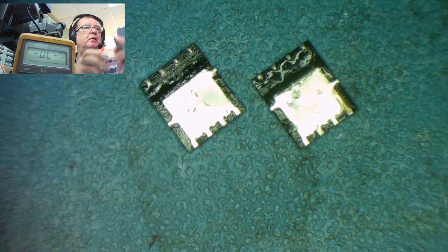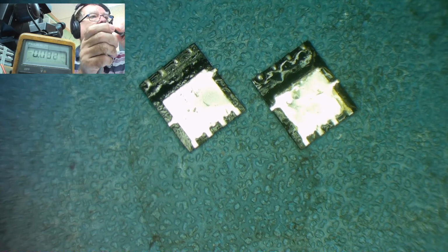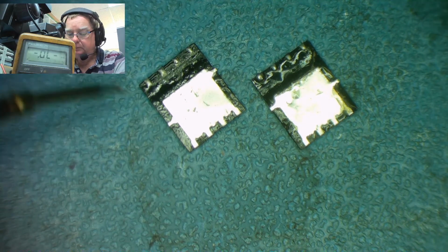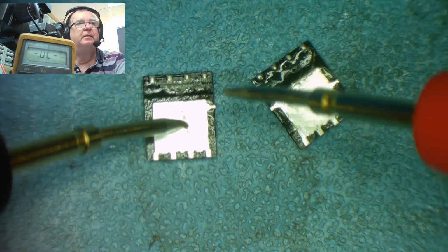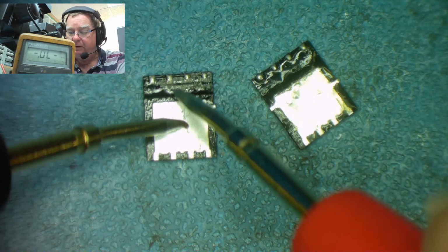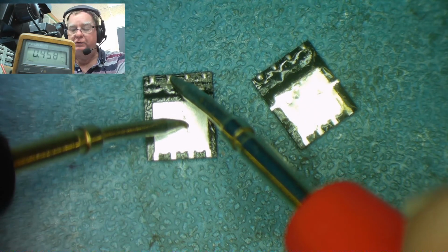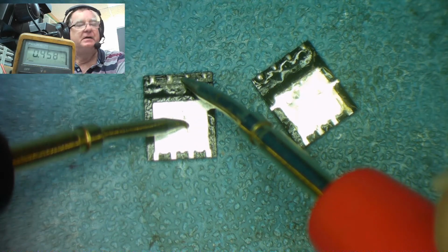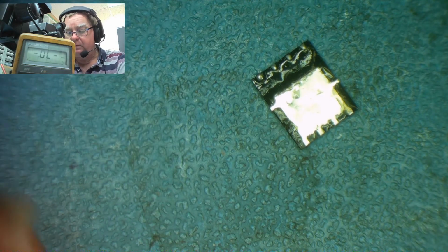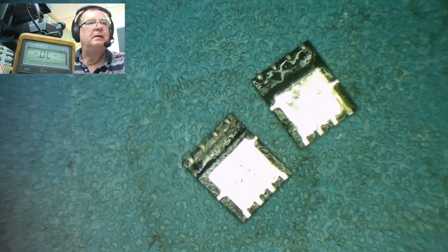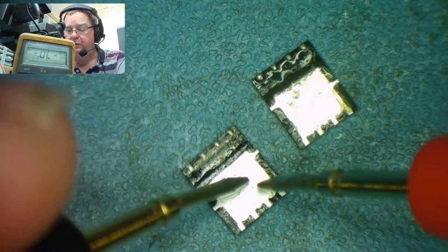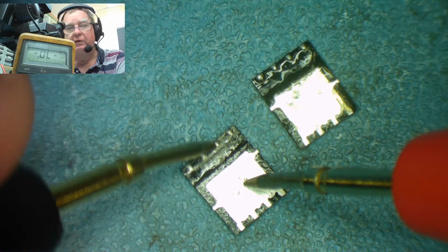So if I get the test probes and put them together, 0, yeah? No. Let's look at these. I'm expecting it, really, one of these middle two will definitely be source, or drain. I'm not sure, whichever way around they are. So there you see like a diode junction, and the other way, turn that back over, little bugger, it moves out of view and turned upside down. Okay, so once again, positive on here, we see the diode junction. The other way around, we're not seeing anything, yeah?